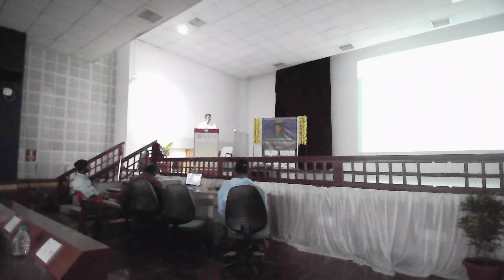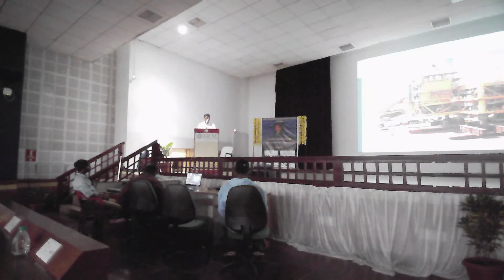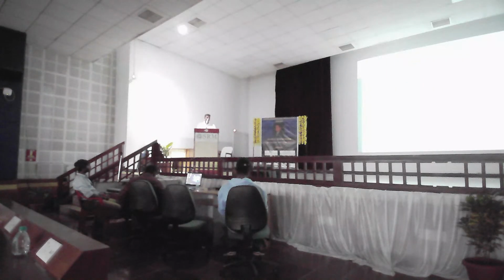You can see these are the various scenarios. What is shown before is just the topside being loaded out. You can see the possibilities during the load-out cycle. Even in the first stage, you can see all the locations are supported, and in the second stage you may not get full support. So you want to design your structure for all the support conditions, then only it will serve the purpose. This is the skidder load-out image, with the jacket entering the barge.